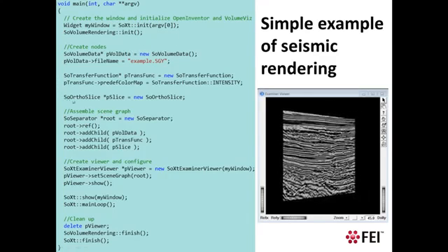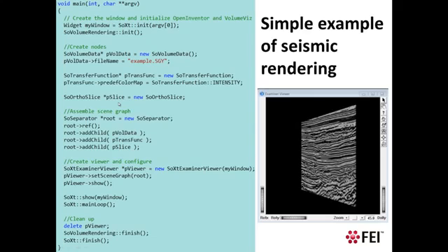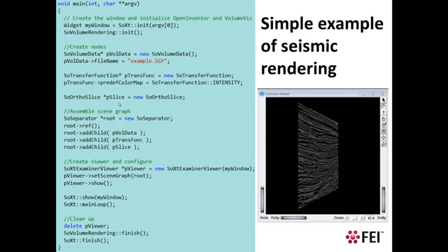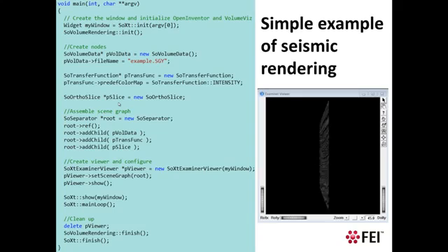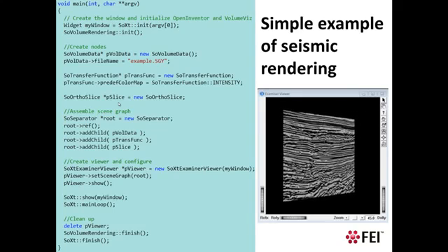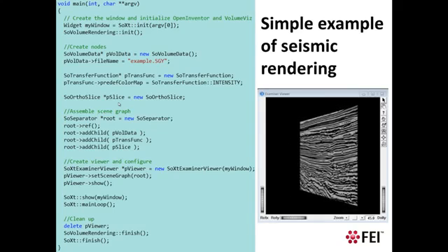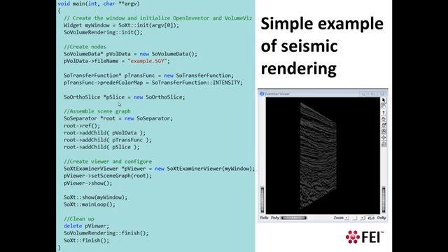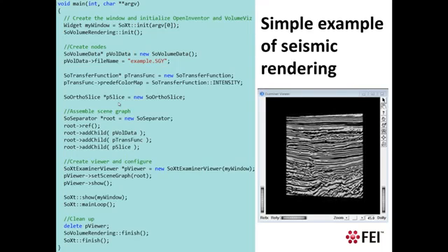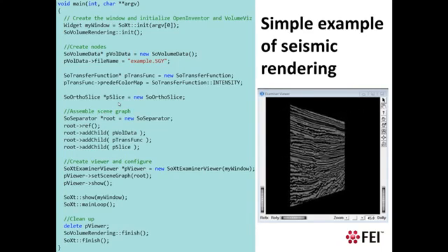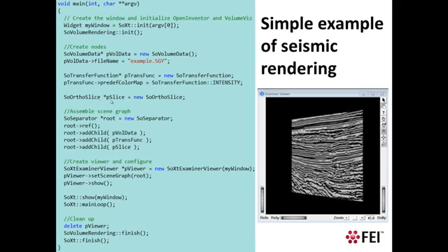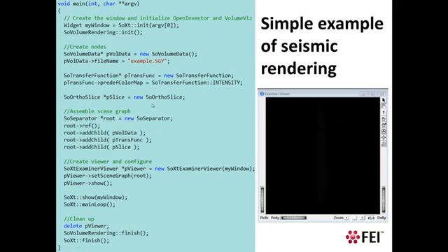Then the scene graph creation, or node instancing. Here, we create a volume data node pointing to the actual data on disk. VolumeViz includes a very advanced SEG-Y reader for reading seismic surveys out of the box. We also create a transfer function ensuring the data to color mapping, and finally the representation, here a slice.